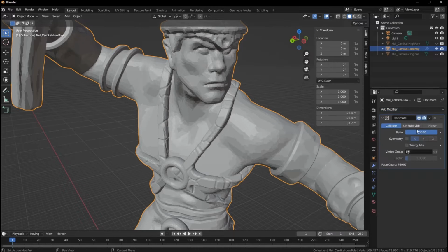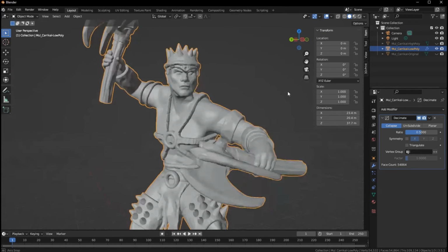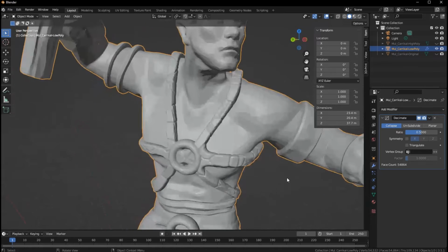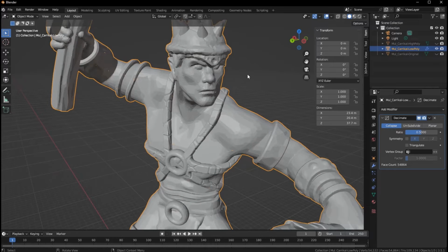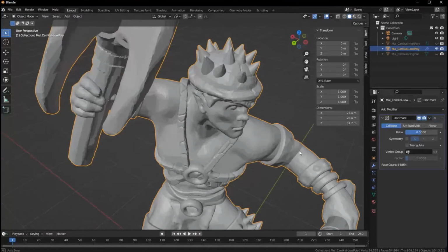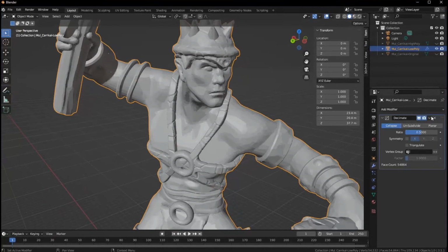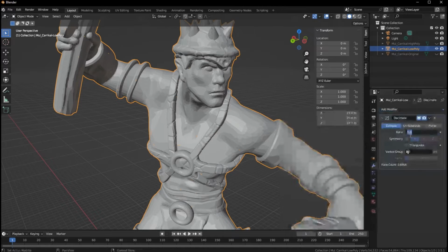So now let's do a little classic decimation. And let's cut this in half, so let's do a 0.5. I like iterative decimation over doing it all at once. There's reasons for that. It comes out of some classic control things with how systems, if you do it in iteration, sometimes do better than doing it all at once. Alright, so I'll accept that. Looks good still. Let's decimate again. Let's cut it in half again.